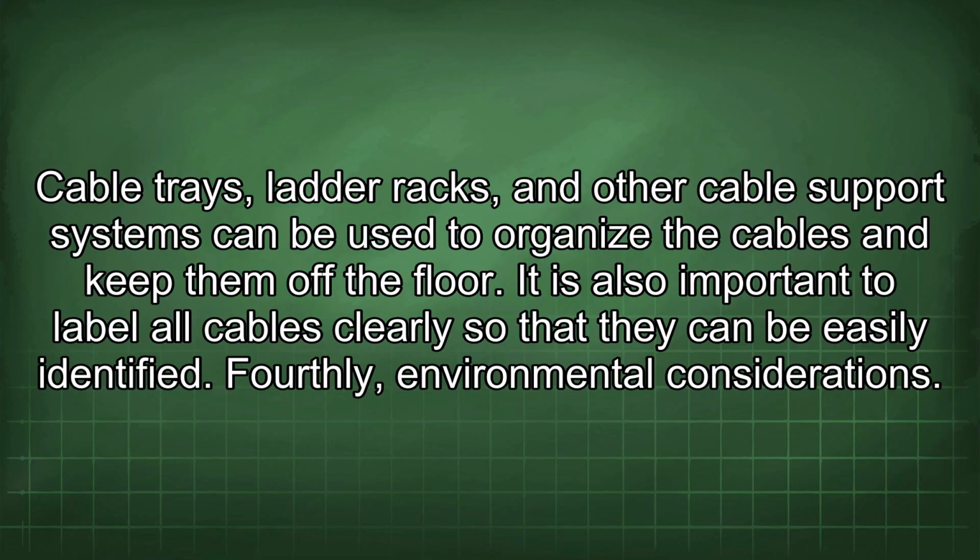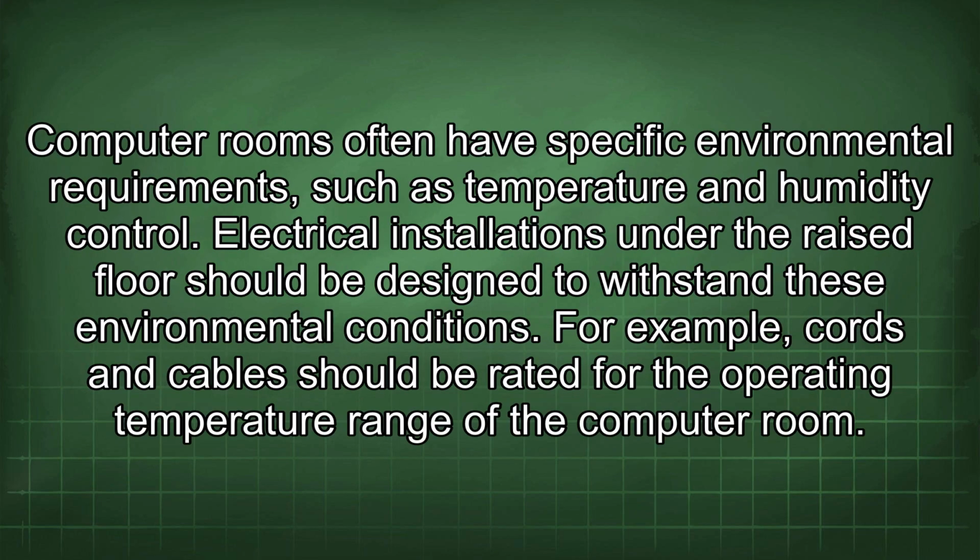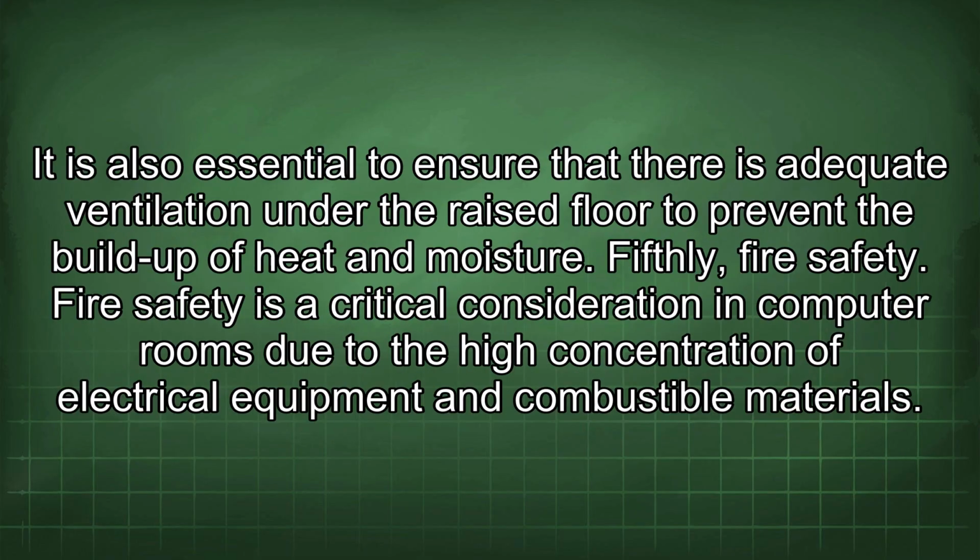Fourthly, environmental considerations. Computer rooms often have specific environmental requirements, such as temperature and humidity control. Electrical installations under the raised floor should be designed to withstand these environmental conditions. For example, cords and cables should be rated for the operating temperature range of the computer room. It is also essential to ensure that there is adequate ventilation under the raised floor to prevent the buildup of heat and moisture.